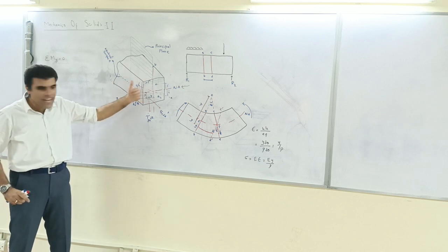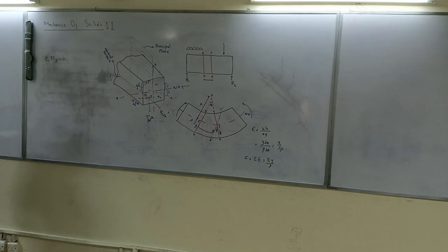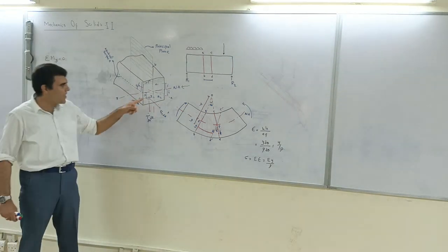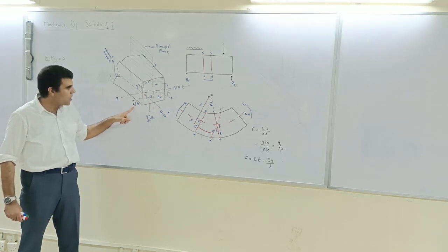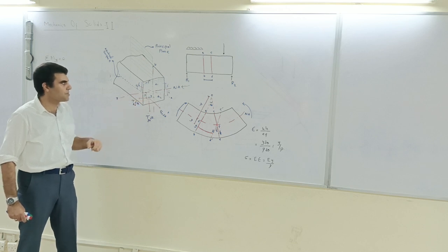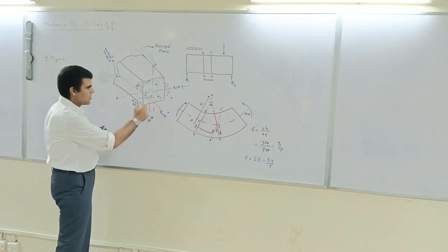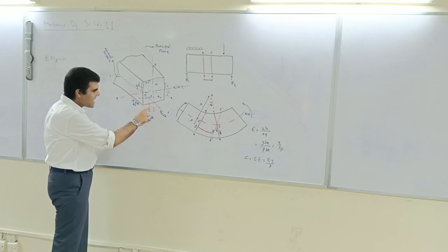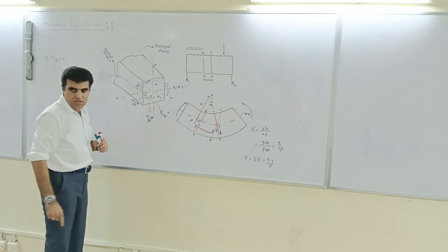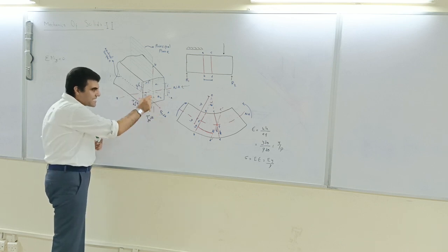So about the y-axis, what are the moments? What is that force? Tau zx dA? Or which force causes moment about the y-axis? Stress xx dA into z. Yes, stress xx times z.